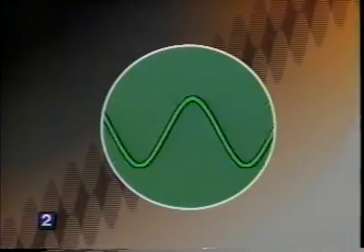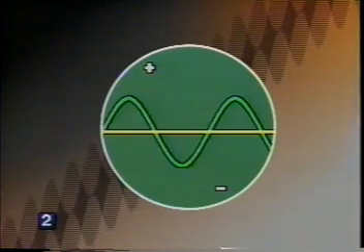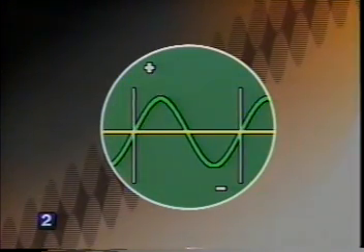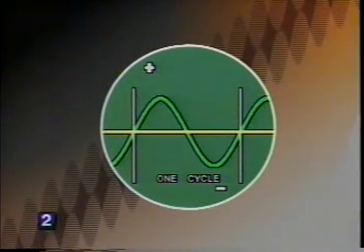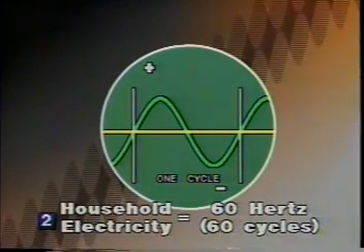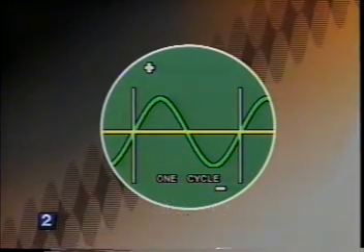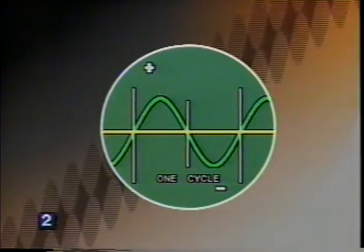Alternating current can be thought of as a series of sine waves that alternate from a positive charge to a negative charge. One change from positive to negative is one cycle. In most homes, one cycle of alternating current is generated at a rate of 60 times per second. The number of cycles per second is known as frequency. The high-voltage circuit in a microwave oven operates using the positive and negative portion of each sine wave.